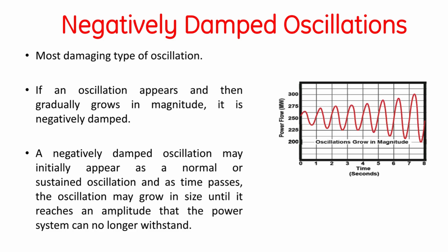Wow. So it sounds like the biggest vulnerability here isn't necessarily the thing that started the oscillation. Often not, no. But rather the state of the grid and its control systems at that moment, the thing that determines whether the damping is positive, 0, or negative. You've hit the nail on the head. The transition from a harmless, quickly dying oscillation to a catastrophic, growing one can hinge entirely on the system's operating point, the tuning of its controllers, that very thin margin between stability and instability.